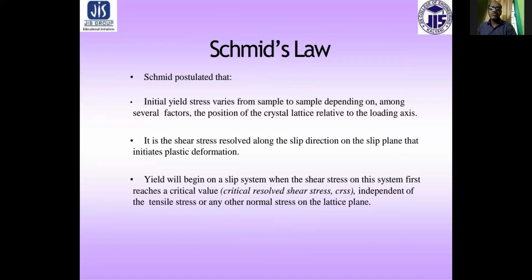If the shear stress resolved along the slip direction of the slip plane initiates plastic deformation, yield will begin on the slip system when the shear stress of this system first reaches a critical value, that is the critically resolved shear stress, which is independent of tensile stress or any other normal stress on the lattice. So these are the postulates of the Schmid law.